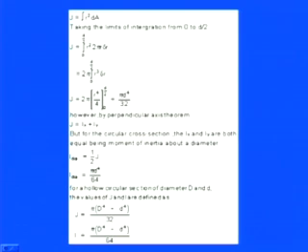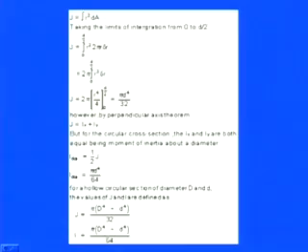But if we have a hollow section in which there are two diameters, the capital D, the outer diameter, and the small d, the inner diameter. So, if we have this kind of section, then we can calculate J, the polar moment of inertia, which is equal to pi times D to the power 4 minus small d to the power 4, divided by 32. Or we can say I, the second moment of area, is equal to pi times D to the power 4 minus small d to the power 4, divided by 64.